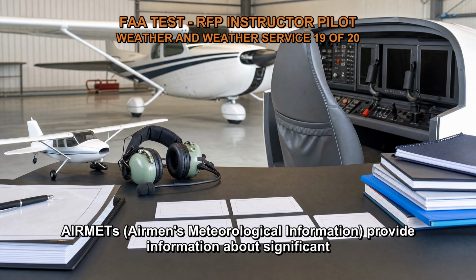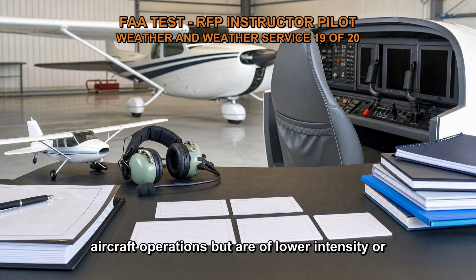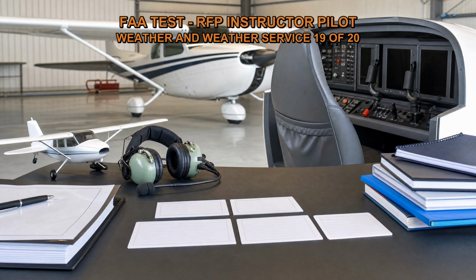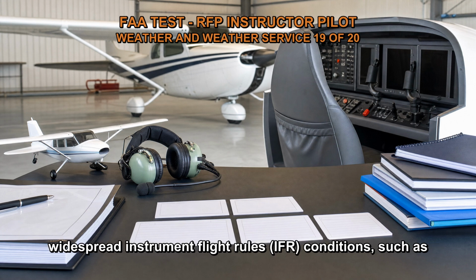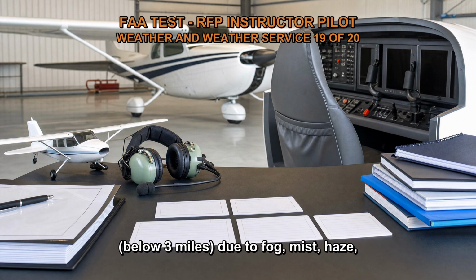AIRMETs, Airmen's Meteorological Information, provide information about significant weather phenomena that may affect the safety of aircraft operations but are of lower intensity or widespread nature compared to SIGMETs. AIRMETs are issued for 3 specific categories. AIRMET Sierra, IFR conditions. This AIRMET includes information about widespread instrument flight rules, IFR, conditions such as low ceilings, below 1,000 feet, and reduced visibility, below 3 miles, due to fog, mist, haze, or precipitation.